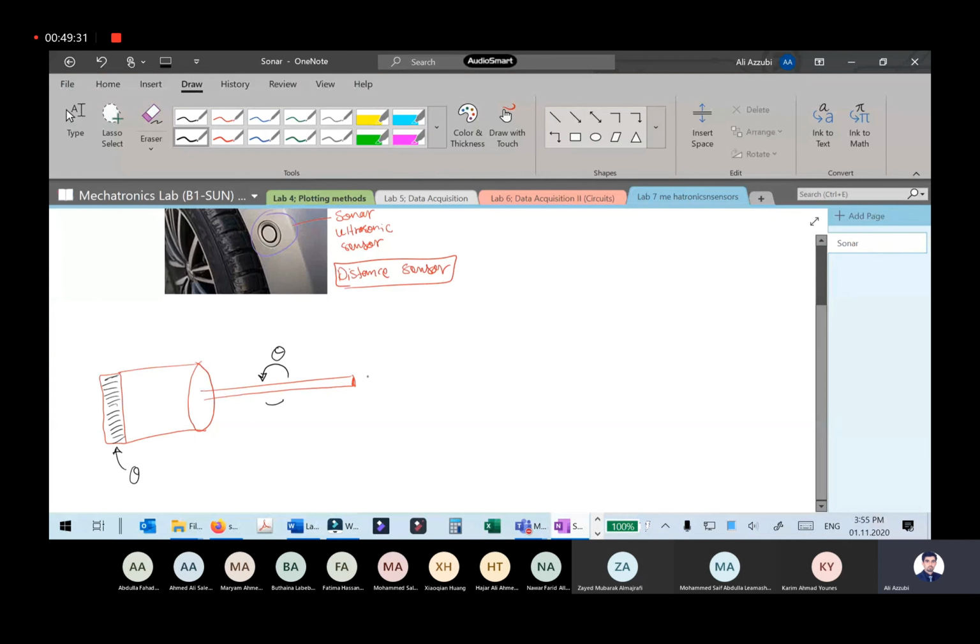Now this motor can drive anything. If it is like a screw drive, imagine that this has a thread like a screw, and here you have a body, and the body is internally threaded. Like this. Now, this theta or angular rotation will be translated into linear motion.